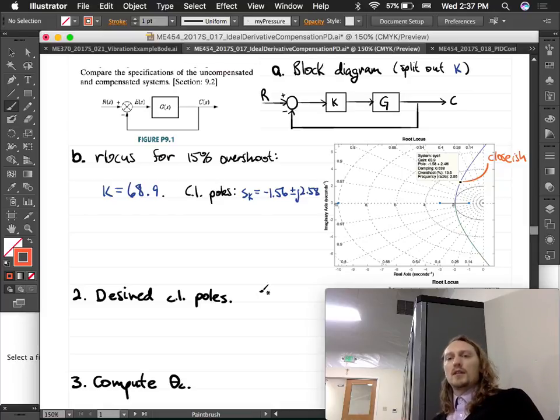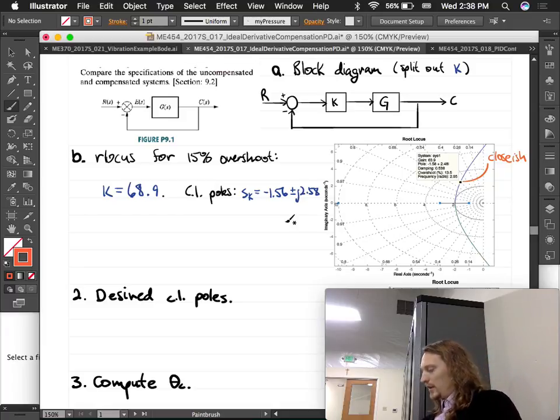Our proportional controller is on the right ray, and we got to the right ray, but are we happy with that? We want to get 3 times faster than that. So what do we do? Scale the vector from the origin to that point. Yes, which is essentially just scaling this complex number by 3, right?